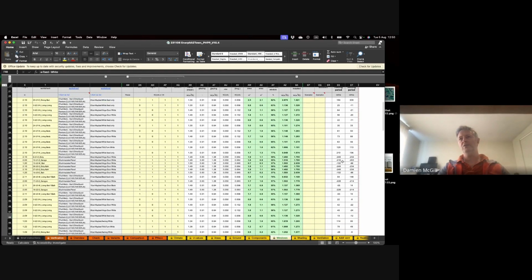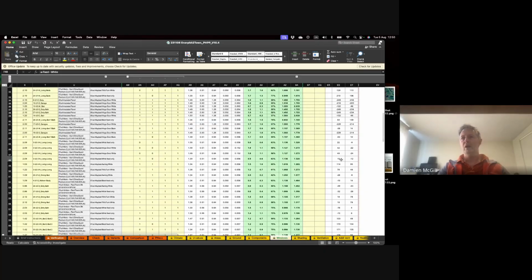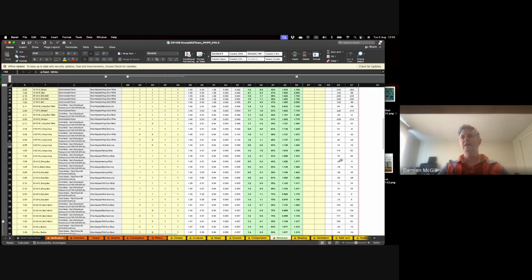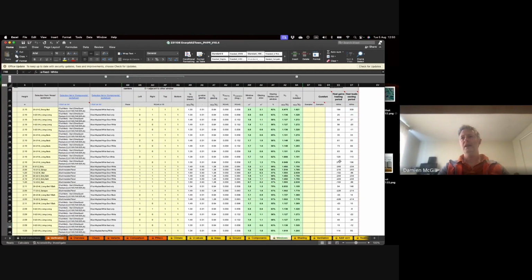So what's really useful here is I can look at this particular window here is losing heat when we need heat. So I can look at, can I make that smaller? Or opposite, if I've got lots of overheating, it's fine. Nothing with great overheating on this. If I see a big number like that, 210, then I can look at how I deal with that as well in the summertime.